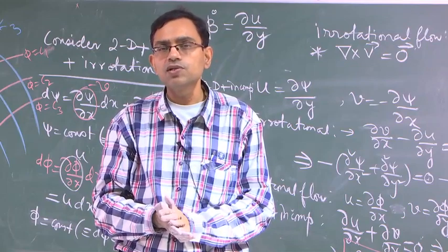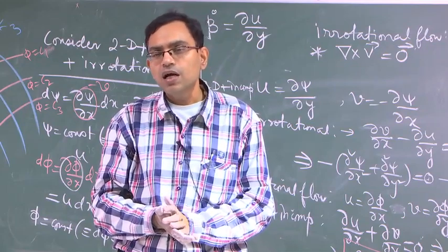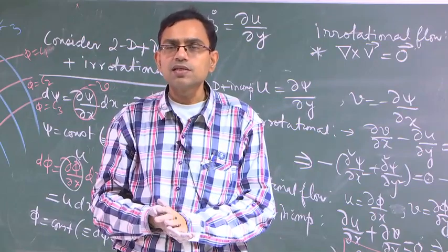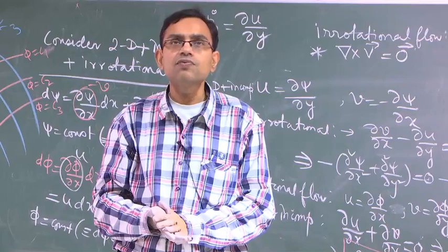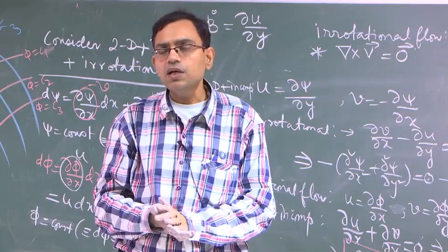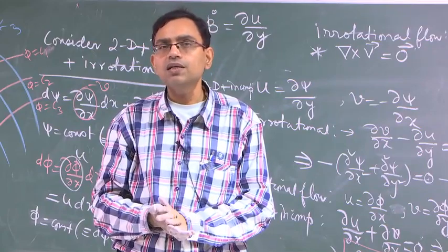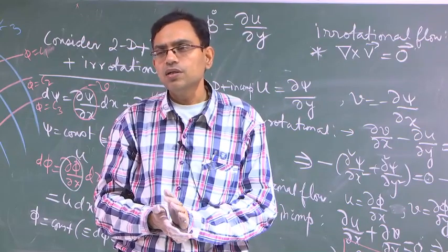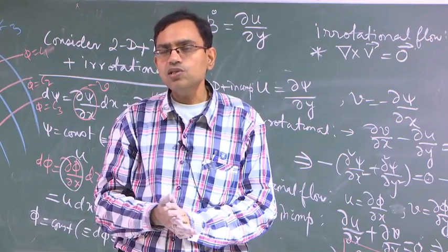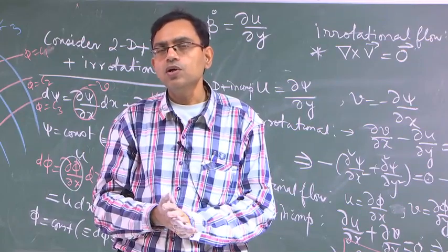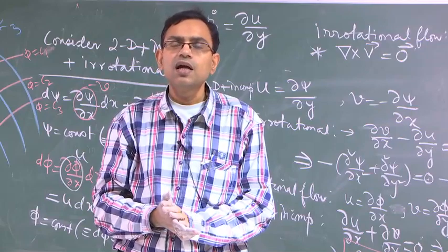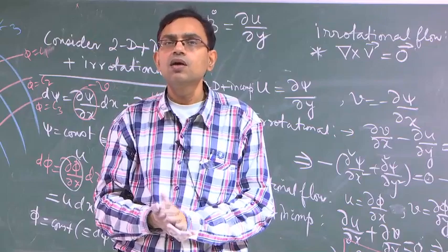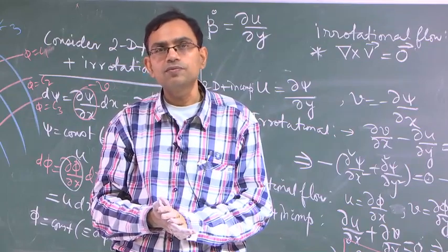Based on these concepts, we will take it further forward and we will study the dynamics of inviscid and viscous flows, where the objective will be eventually to relate the force with the deformation, and for viscous flows the force deformation relationship will eventually make us arrive at the famous equation of motion, which for a very special case boils down to the Navier-Stokes equation.